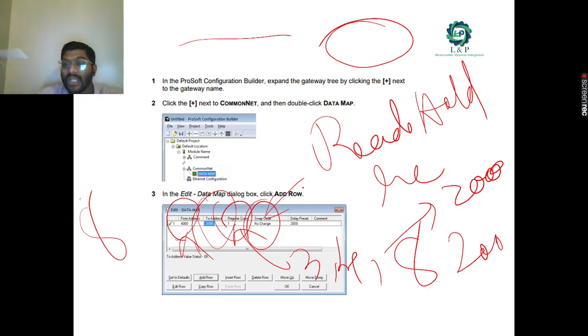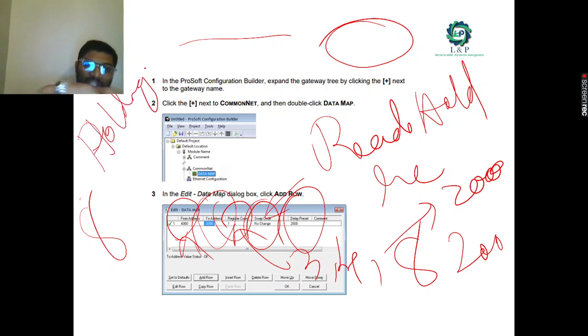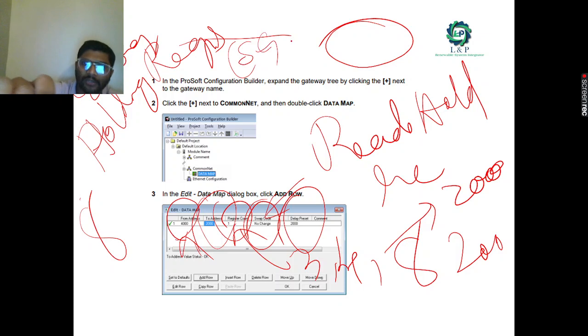And most importantly, what is the delay preset? Delay preset is also very important. You should know what sort of register delay you need. In order to know this, you need to know the field equipment's holding register values. If you are going for energy meters, you need to know the holding register value of the energy meter. Energy meters come from different brands, Siemens, Schneider Electric, and so many others. Even Alphanor also has this energy meter.